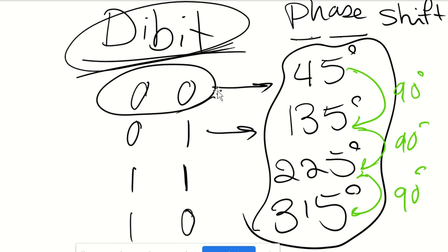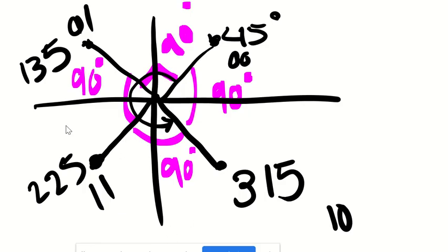This is very common, and the angles that I'm using are common ones, 45 degrees, but it's not written in stone. Other phases can be used. And as you see, for 2 bits, you should have 90 degrees phase change. So in the constellation diagram, you have a nice 2 bits transfer of information.